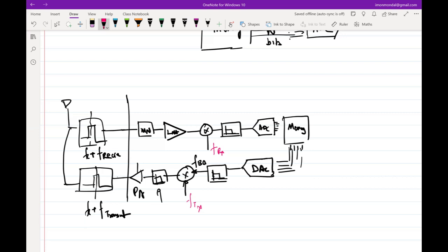So here the down conversion, it is from the textbook, it is minus FC. Whenever you see minus FC, if instead of putting sinusoidals you use complex exponentials, e power FC plus something, then in order to get that e power FC to DC, you have to multiply with minus FC. In principle, that is what is happening. But if you are talking about real signals, then nothing is negative frequency. Everything is positive frequency. It is assumed that it has both positive and negative components when you write trigonometry.